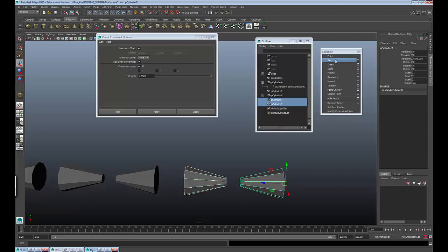If you're using, say, for example, Davey, his knee and elbow controls, I don't know if you noticed, they're always kind of pointing in the direction. The knees are pointing in, or the eyes, when you move the eye controls around, are always following them. That's connected using this aim constraint. Basically, whatever you've selected will always look at the other object.